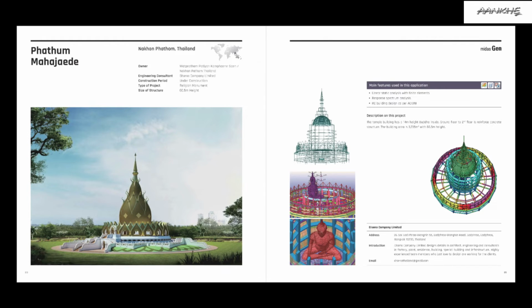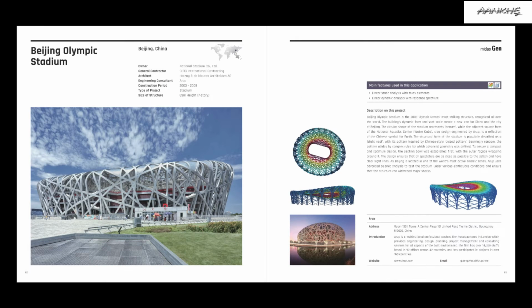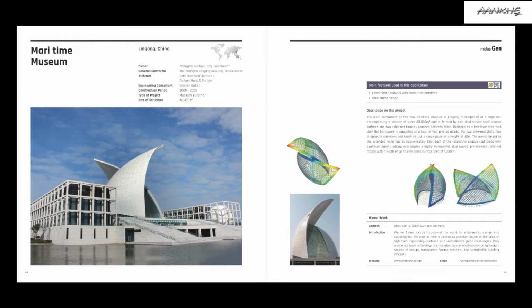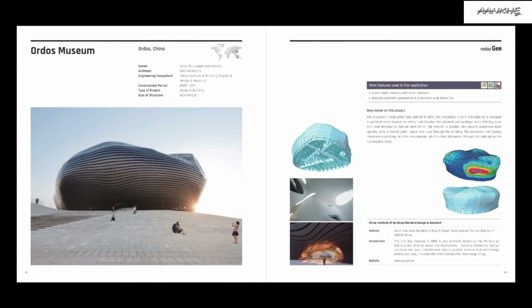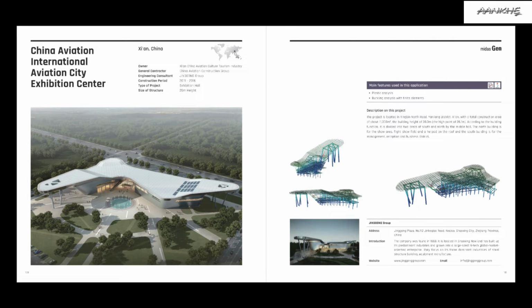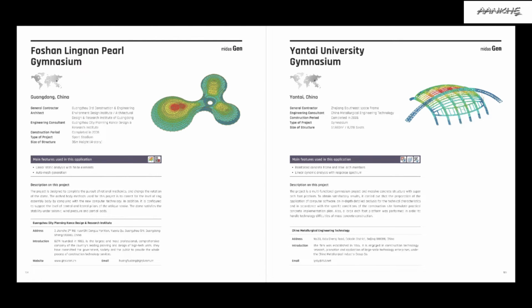But when you come to the generalization of software, always remember that a general software has a wide area of operation. That means, for example, in ETABS, if you do not provide a diaphragm, you cannot apply the seismic loads, right? But here in Gen, without defining the diaphragm, you can also provide the seismic loads, right? So there are several things. Many people who are acquainted with other software may say differently to this opinion. So it's up to them, because whoever is using a software knows only the pros and cons of it.